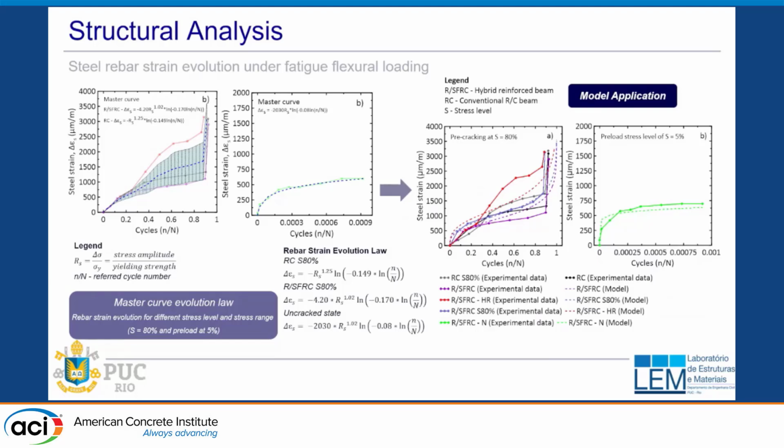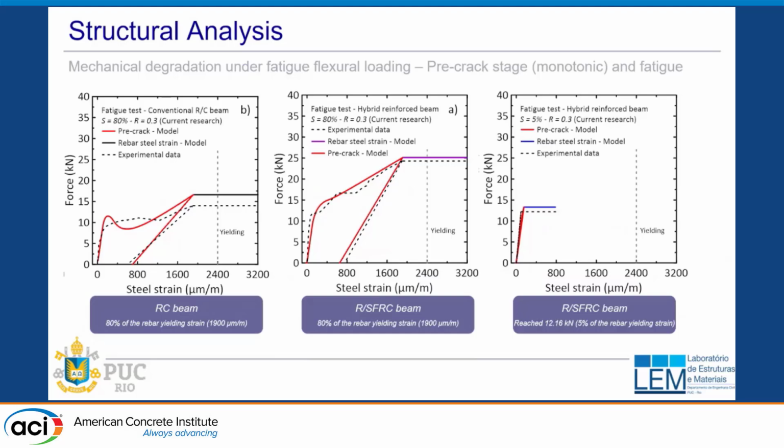At this point, the case converts into coming up with a master curve that can be an average of all of the values that we are using as a function of the stress ratio. For different stress ratios, we get a master curve for the strain in the steel as a function of the number of cycles. Using that, this curve is what is used to generate for different stress levels. We would be able to develop the strains, and the strains are used to simulate the response of the section depending on the creep level.